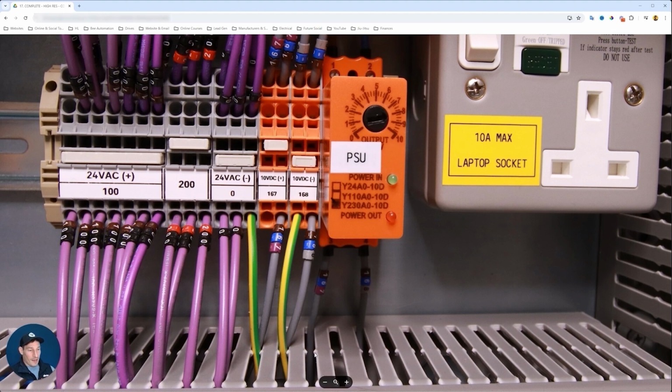And then you can see here coming out on the DC side, I'm then feeding that into a couple of terminal blocks just to make the wiring a little bit easier. I didn't necessarily have to do that for this panel, but I just think it makes it better and easier to maintain, fault find, service. It's all very clear. So yeah, that's what I've done. So on the positive 10 volt DC side and the negative DC side, you can see the numbers of the circuits here. I've also earthed the 0 volts, which we'll get into in another lesson.